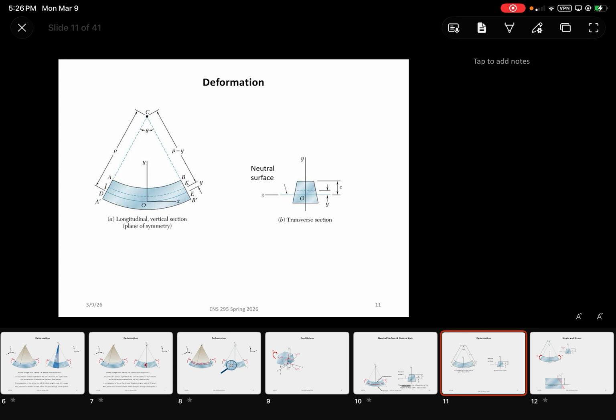So again, as I mentioned, along the neutral axis, we know that the strain is not going to be present. There's no strain on the neutral axis because it's a point where there's no stress. No stress means no strain. So on the neutral axis, NA, looking at an XY plane, the strain in the X direction has to equal 0.